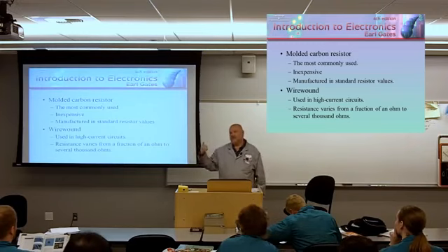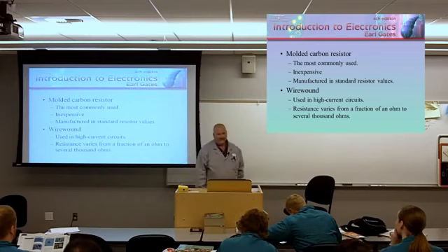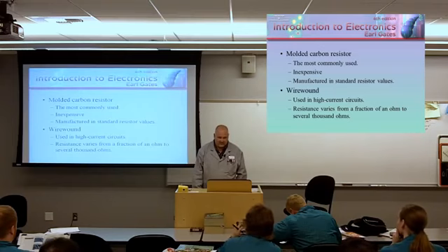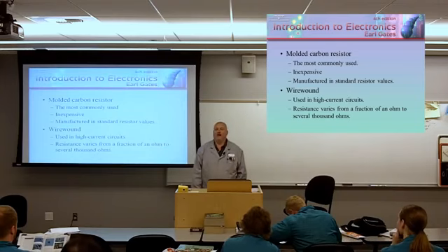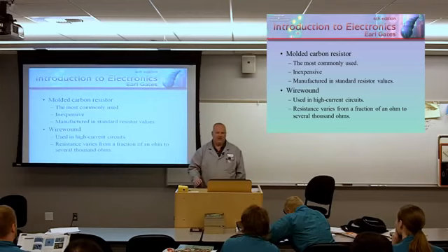Make sense? So resistors are the same thing. When we say they come in standard sizes, they come in standard sizes. Don't expect to go out and find a 103.5 ohm resistor. Don't expect to find that on the market. You could go buy a package of 100 ohm resistors that are plus or minus 10% and start going through to see if you could find one that's 103.5. But an engineer is never going to specify a 103.5 ohm resistor in the circuit. They'll say, I want a 100 ohm resistor. Standard sizes.